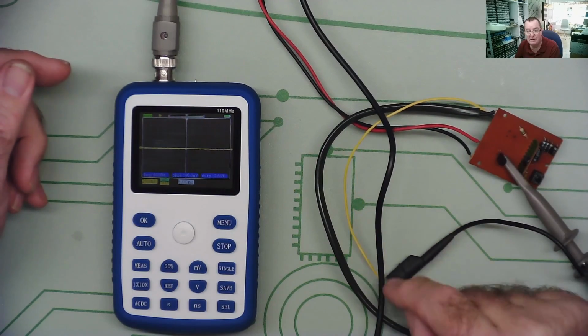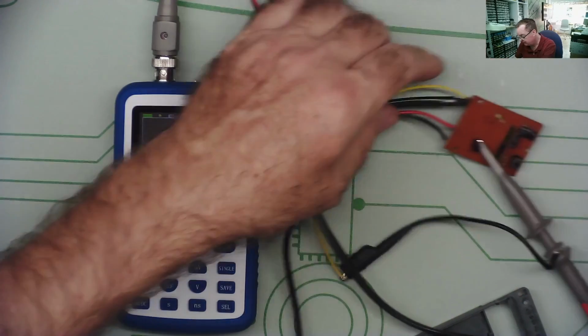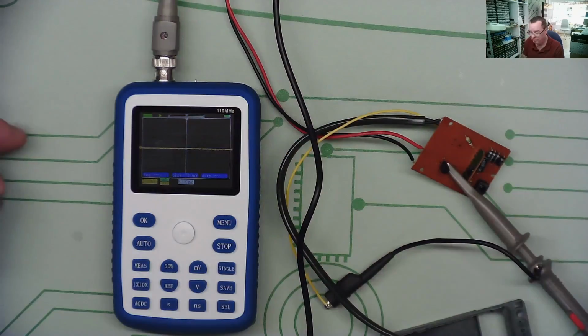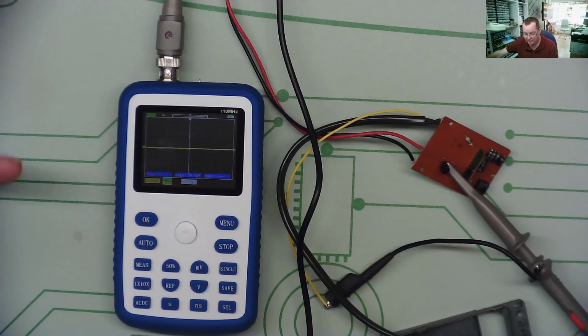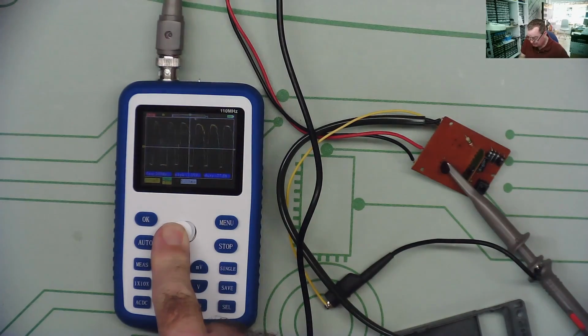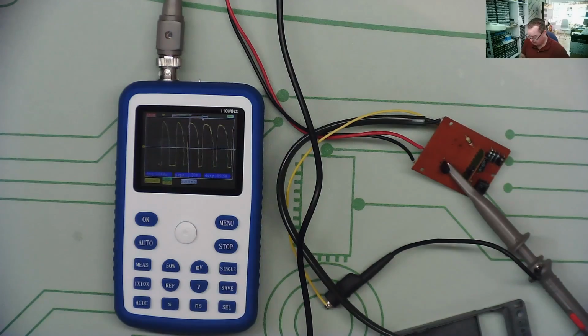I've connected ground of the oscilloscope to hot ground on the PCB, and I attached the probe to the gate of the thyristor. So let's switch this on and let's see what this is actually doing. So we switch it on, you can probably see the bulb flashing or the light from it. And you can see there the waveform that is being driven. I can go to single mode and we can just actually have a look. You can see this is the drive and you can see that it's switching on part way through the cycle.